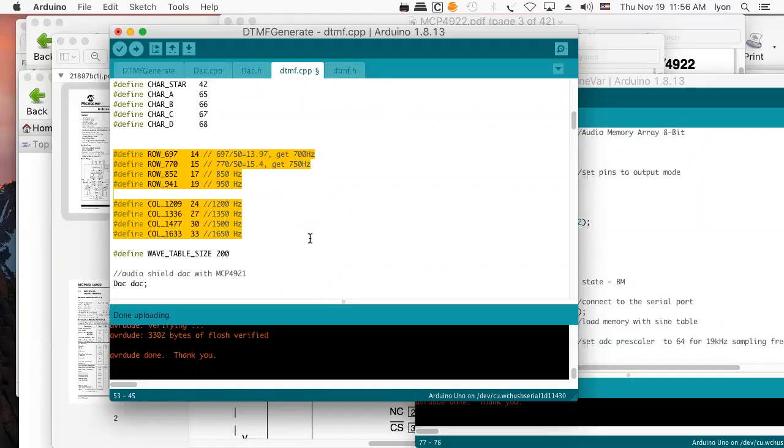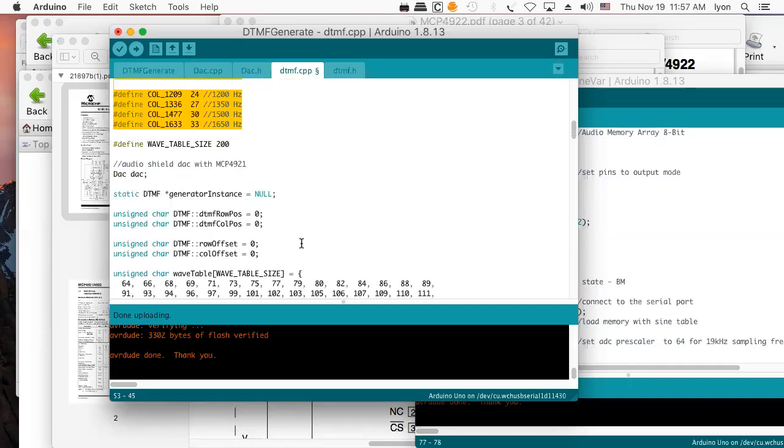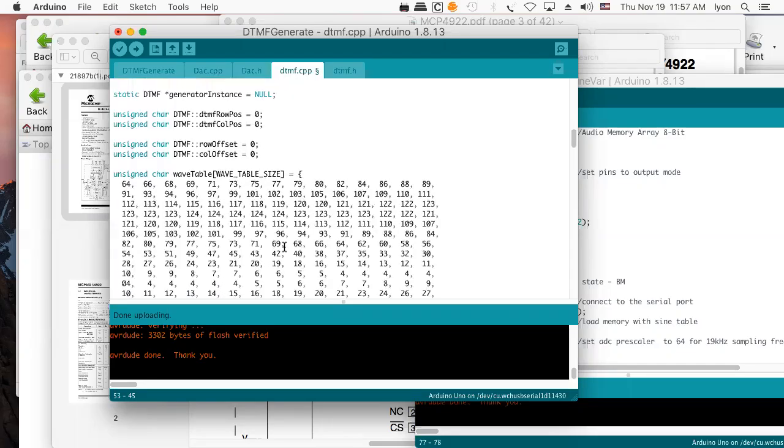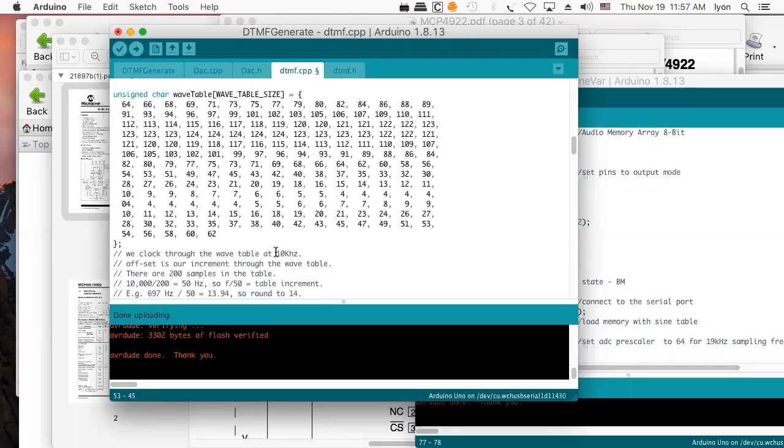If you reparameterize it in terms of wavetable size and then double the size of the wavetable, you don't have to recompute everything, because all of these numbers can be backed out from the size of the wavetable and your sample rate. Those are the two factors which you have control over. But wait, I just kind of gave it away. What else can I do? I could change my sample rate, right? Let's leave the wavetable alone. Let's change the sample rate by doubling it. I could sample at 20 kilohertz.